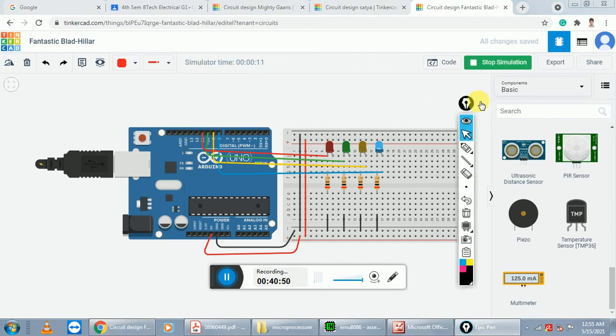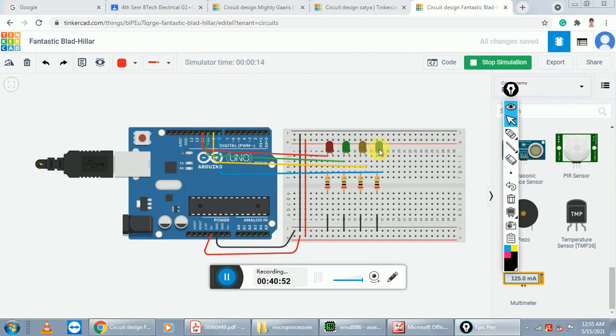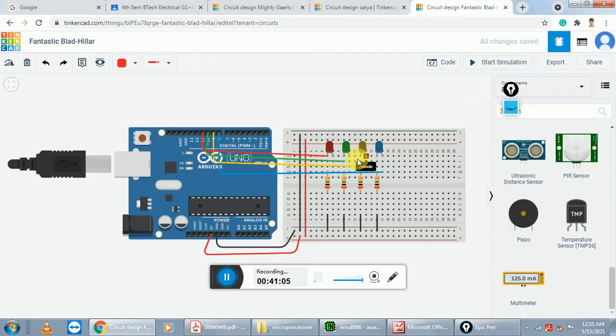Okay, our only two LEDs blink. Okay, so here we made a wrong connection, so stop this. Basically this connects to this. Okay, here we connected with the cathode, so these pins should connect with the anode.